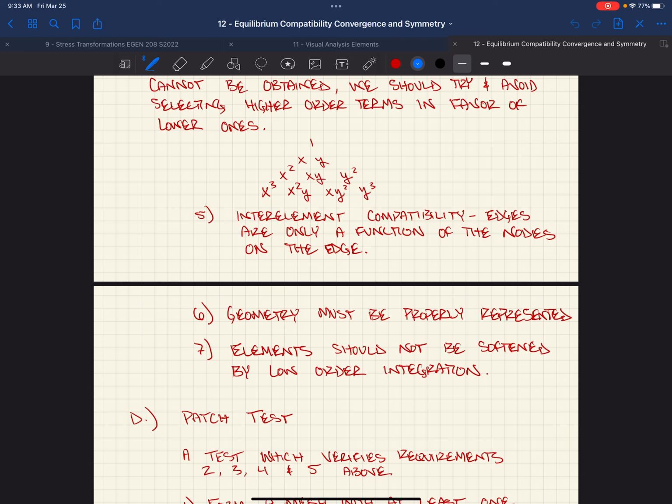It's only going to be exact in a beam sense if you didn't have any uniform load between the endpoints of your beam. We went through it in the notes. It shows how displacement changes along the element. Yep. But so having it be cubic instead of quartic adds stiffness?